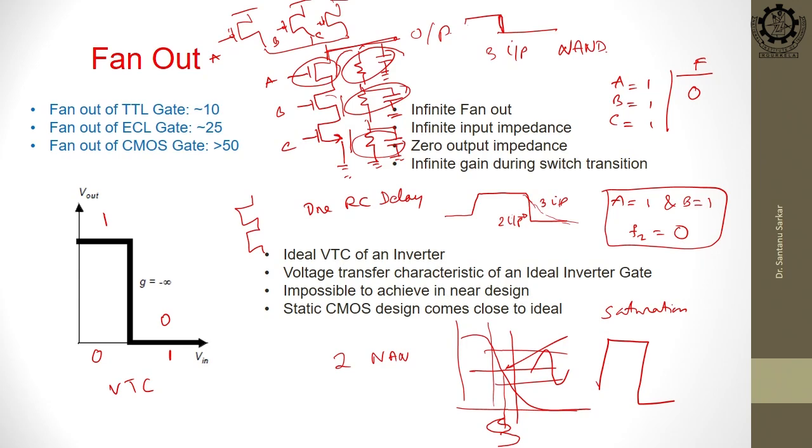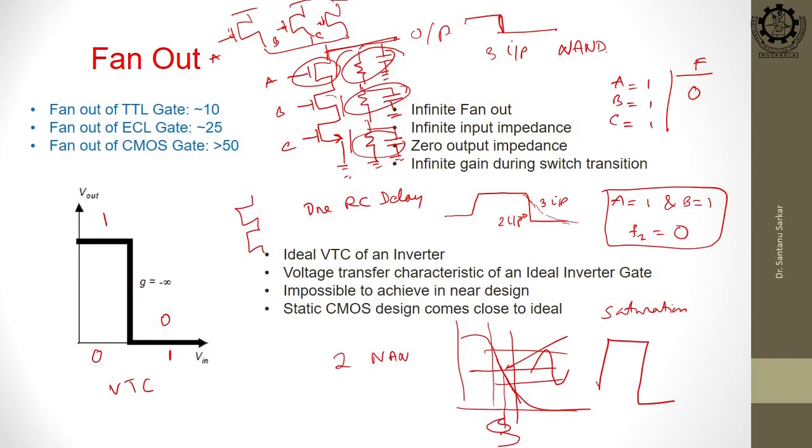Getting my point? If you think of an inverting op amp amplifier, this zone will be your amplified zone, if you recall the op amp. And if this signal is a little bit higher, what will happen? Your output will be clamped, saturated, plus and minus VCC. So, characteristic wise it is the same.